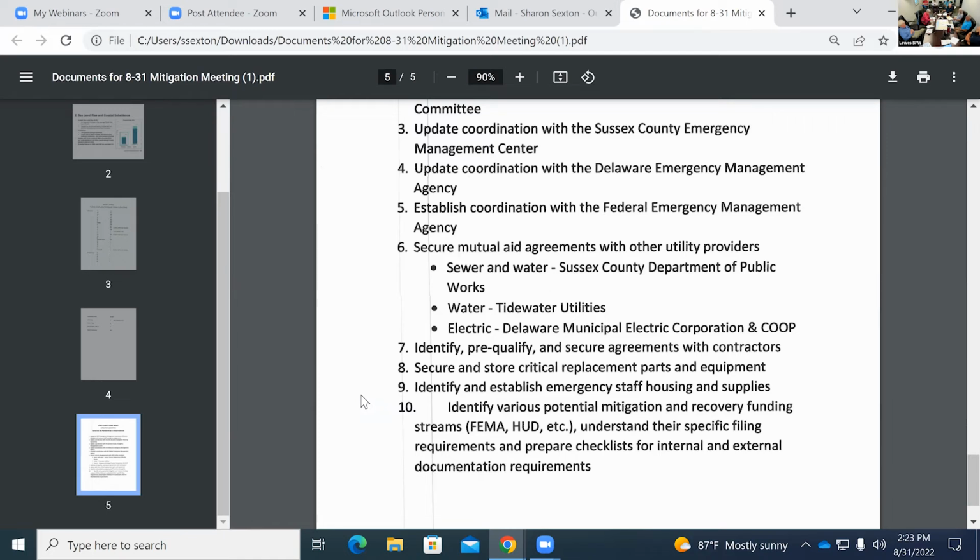There's a big concern on the Canary Creek side of New Road from Denmark's perspective, from saltwater intrusion, and then the transmissivity. Looking at it from a heat map perspective, where the current wells are, you couldn't have picked a better space. But as soon as you step out, it gets really tough to find a good piece of land. And, of course, public objection to towers.